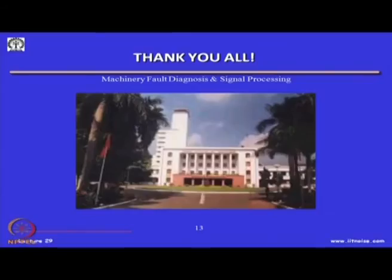And vibration analysis itself can be done in many ways: time domain signal analysis, frequency domain, time frequency, or cepstrum analysis. And then we can not only know the gearbox fault conditions, but also actually diagnose and find out the real cause of the fault in a gearbox. Thank you.